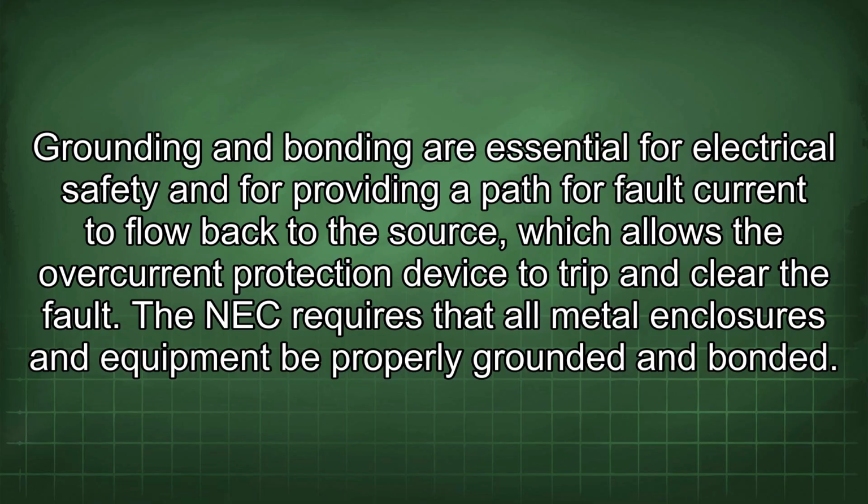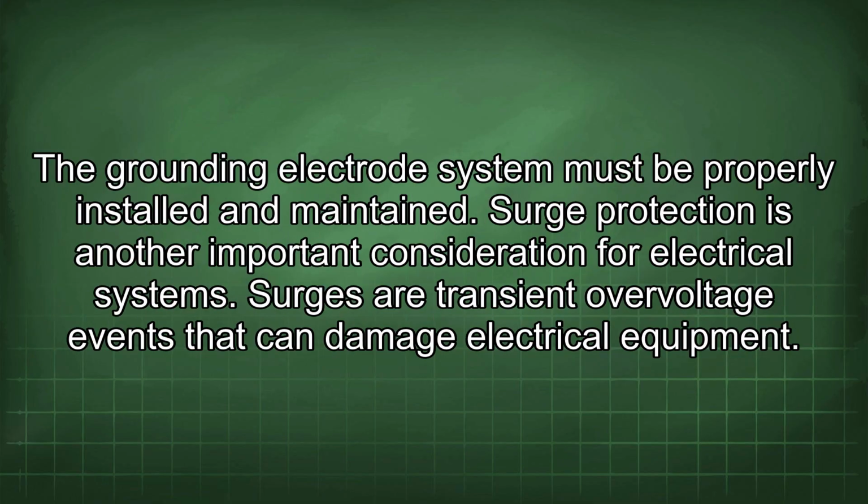The NEC requires that all metal enclosures and equipment be properly grounded and bonded. The grounding electrode system must be properly installed and maintained. Surge protection is another important consideration for electrical systems.